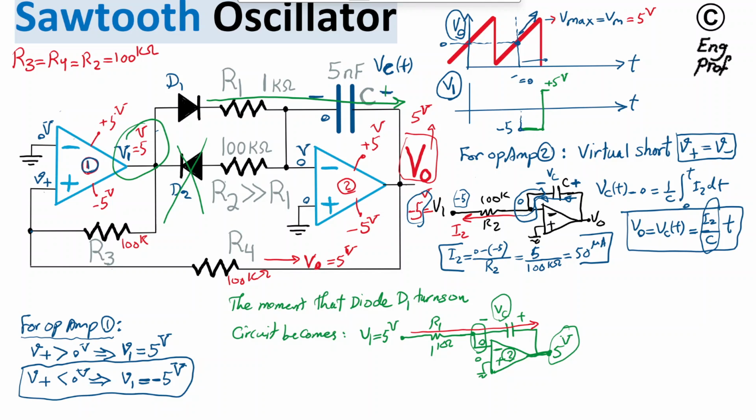This whole thing happens way faster than before because now the value of resistor 1K is much smaller than the R200K by a factor of 100. So whatever happened before that I described here and I described here is going to happen 100 times faster. So let's just write down the equation one more time. Equation is like this. Voltage of cap at time t minus initial condition, so V cap initially, is equal to, okay, same as we saw here, but now is going to be